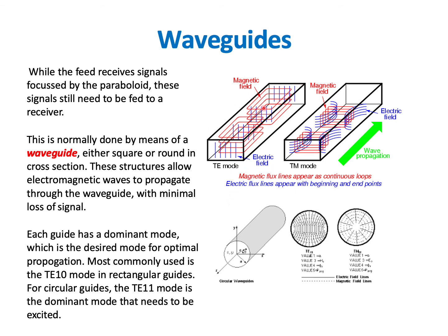So these are metal guides that allow electromagnetic radiation to propagate down them, and they have to be tuned to the frequencies we want to propagate, because otherwise frequencies that these guides aren't tuned to will be heavily attenuated, and the electromagnetic wave might not even make it down the entire waveguide if the waveguide isn't tuned for the right frequency.